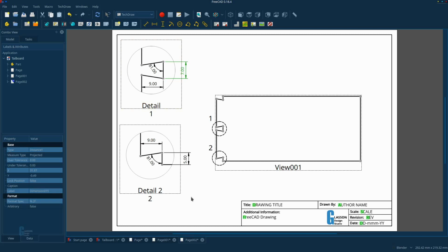The use of multiple views would be very, very handy for when you're doing, say, draw sides with houndstooth dovetails, where you have a dovetail of 2 different depths. Because then you could use one of the detail views to show the smaller dovetail pin, another to do the larger pin, and a third to do the half pins, like we've done here. So this has been a fairly high level introduction to it.